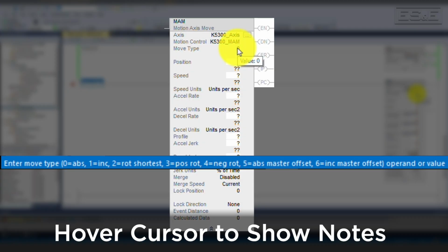Quick tip here. If you hover your mouse over the field you would like to edit, the bottom left-hand corner of the Logic Designer window will show a note that helps with the current field. In this case, it clearly tells us 0 means ABS or absolute, and 1 means INC or incremental.